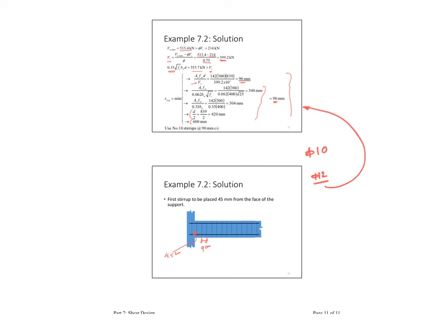It could go, for example, to 10 centimeters or 12 and a half. A 12 and a half is also a good number, or 15 centimeters spacing between the stirrups. Why did I say 12 and a half? Because simply, every 25 centimeters you put 2 stirrups, so they can easily do this on the site.